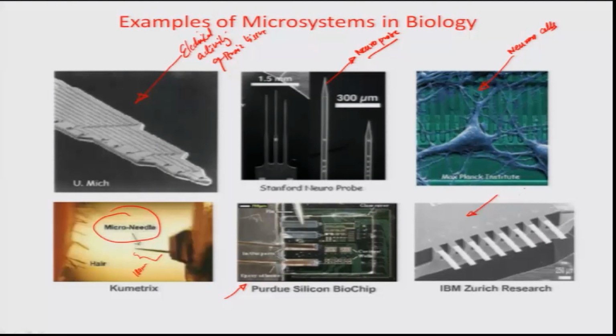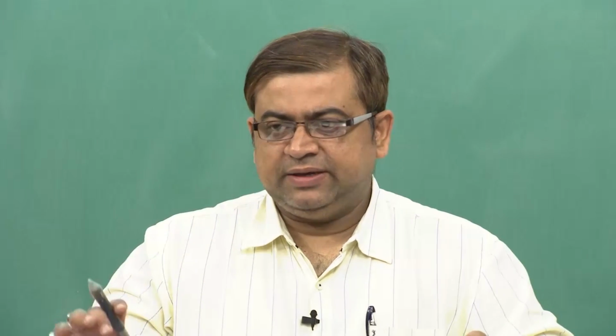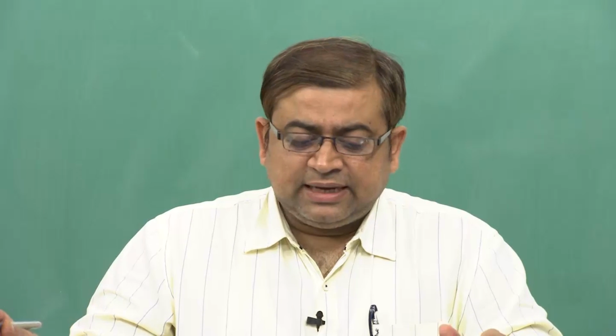These are a set of cantilever arrays again, which are made with an intention of biomolecular detection. So, the idea is that if I had a sequence of molecules which are immobilized, let us say some kind of a single stranded DNA molecule which is immobilized onto these surfaces, and they bind to some other molecules which are target molecules, there is going to be some deflection because of the change of the surface energy, which is actually given by something called Stoney's equation, where the surface energy change between both surfaces of a small cantilever would result effectively in a deflection.